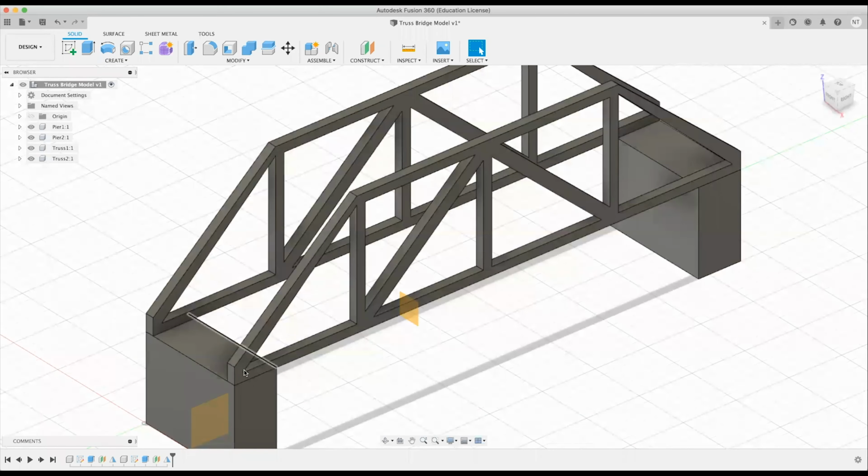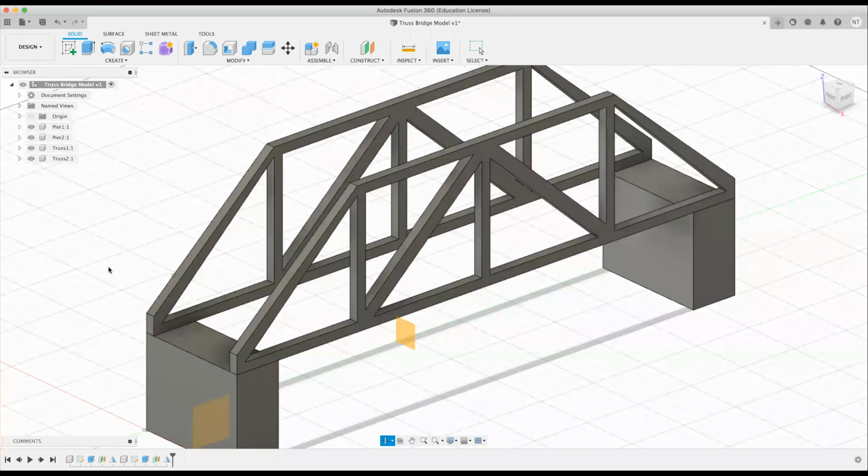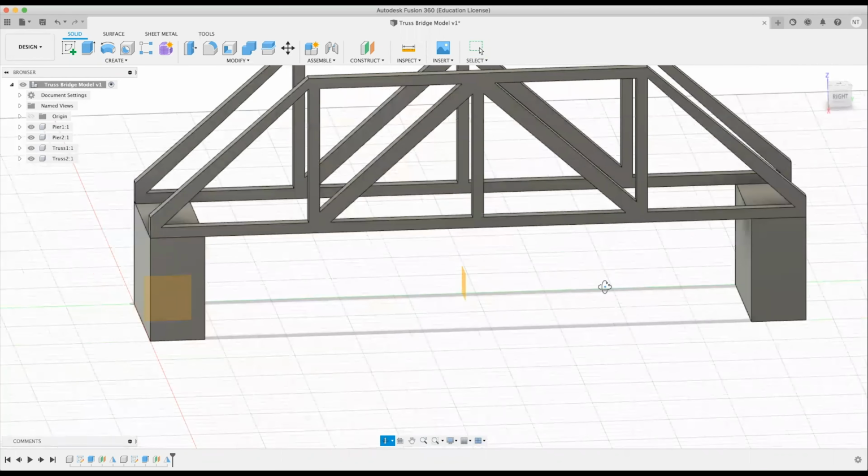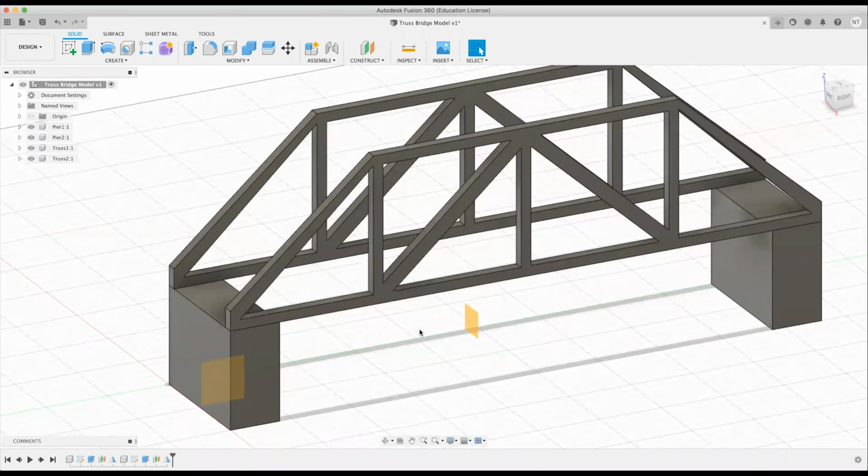Now we'll make the beams that are supporting the deck itself. And ordinarily what you would have are piers. Just to give everyone a bit more context of how a bridge design might actually look in a more complicated scenario, these would be either your piers or abutments. In our case, we're going to simplify the model and call them our abutments, so the ends of the bridge where it's supported. But what you might normally have is also an abutment, or what's called a pier, in the middle of the bridge. And that's going to be reducing your span length in the horizontal direction. That just means that your deck will be much better supported, and that'll help you with your short-term and long-term deflection criteria.